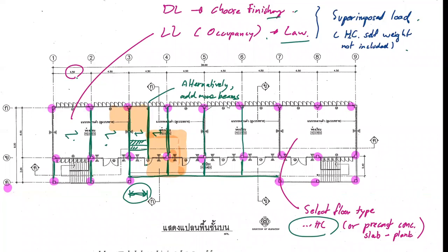Okay, Napat, is that okay? Okay, I just wonder why you mentioned just HC and precast slab only. Or you mean metal deck? Yes. Yeah, you can create the composite system out of hollow core and precast.